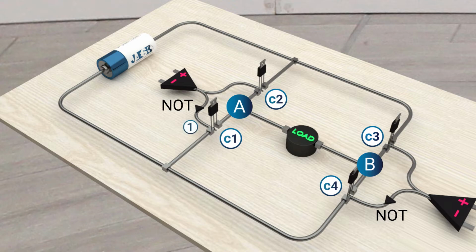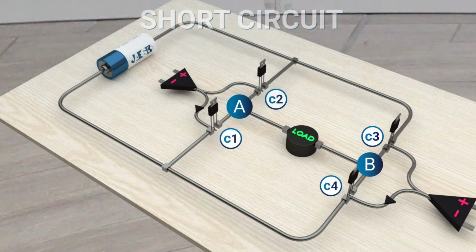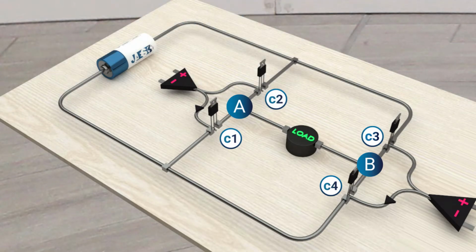So you can see that the output branch of the comparator is equipped with exclusive logic. It means that when C1 is open, C2 will be closed and vice versa. We can never turn on C1 and C2 simultaneously because this will cause the DC circuit to short circuit. If we turn C1 on, which gives the cell voltage at point A, and if we turn C2 on, we'll obtain a voltage equal to 0. Same thing for point B.